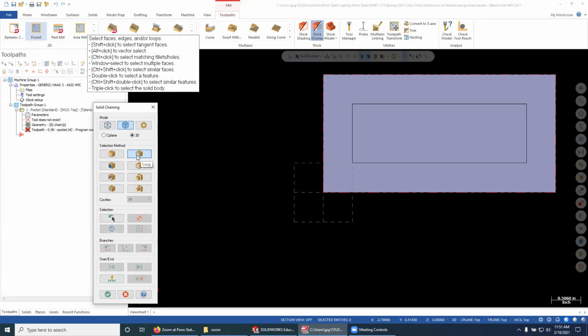What I'm going to use is this loop. So in previous versions, it's been actually difficult to even open up a solid part, which is why we had often gone to the IGES files, and then when we bring those in, typically using the edge curves so that we have more of a wireframe geometry that we can select. But in this case, I can still use this.